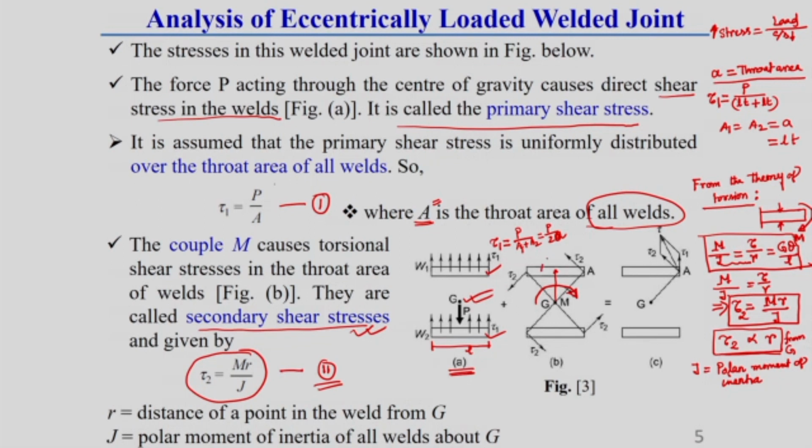Here there are two welds. Let us say one weld has polar moment of inertia J1 and the other weld has polar moment of inertia J2. So, in this case we should consider the polar moment of inertia as J1 plus J2. I will explain in detail how to find the polar moment of inertia of this weld in a subsequent slide. And you know what this G is: G is called shear modulus, or modulus of rigidity.